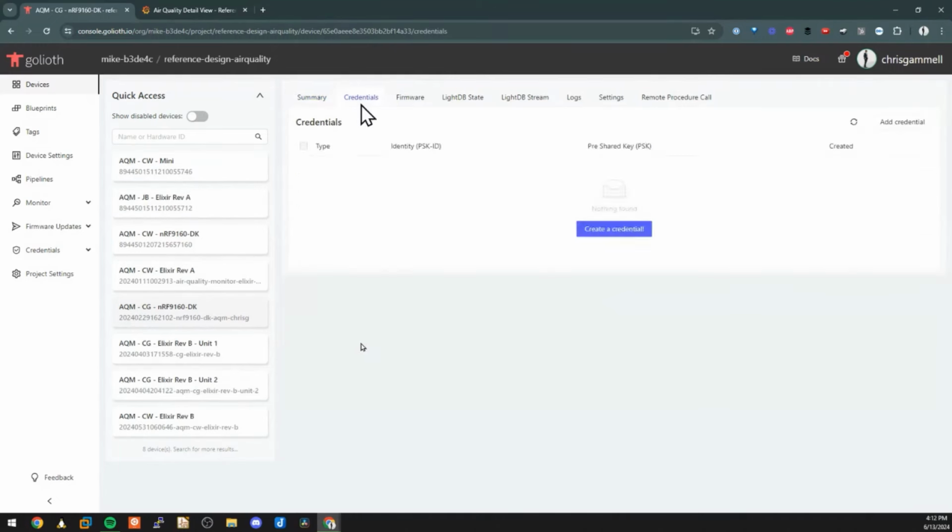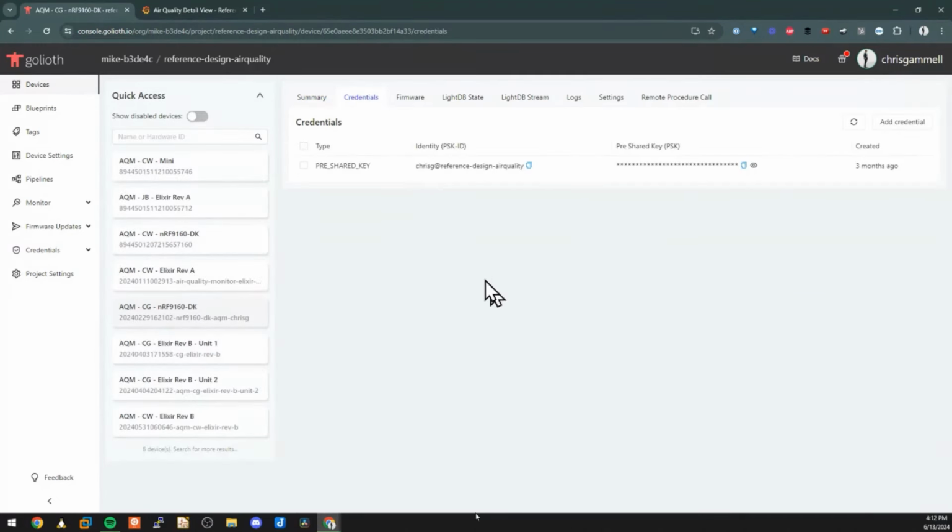One very important one is that you can't talk to Golioth unless you're doing so securely, using DTLS and PSK ID and PSK. PSK is pre-shared key, and that's because basically the cloud is provisioning a credential for you, passing it down to the device, and then you program that onto the device. That's really the easiest way to get started. We also have certificates, which are a little bit more involved, but ultimately what you're going to be doing as you go into production.